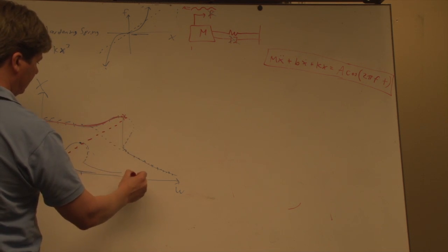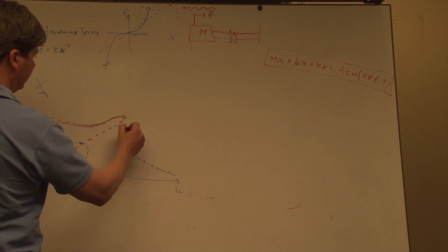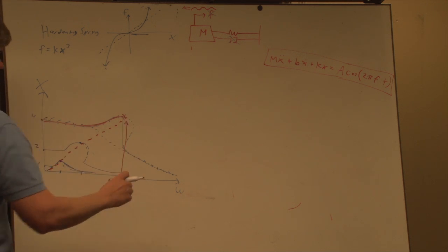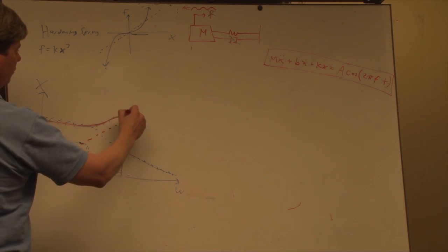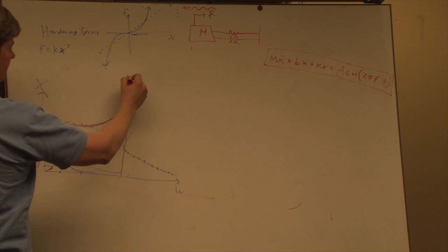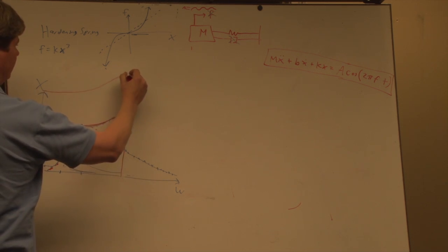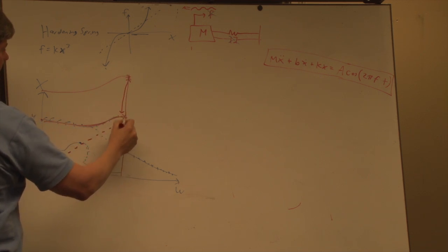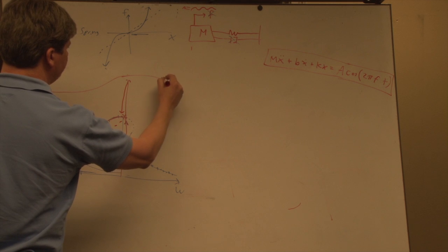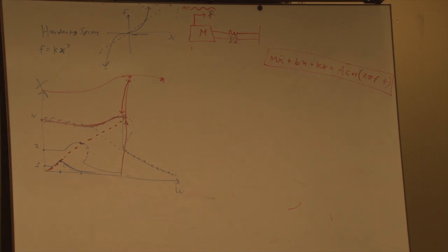But you cannot take this path to get to that point. You can't oscillate really fast and increase the amplitude and get to that point. What you'd have to do is get the amplitude way beyond where that's a resonant, where you're actually at a resonant curve here at a really high amplitude. Then once you have resonance, drop back down in amplitude, and it'll keep its resonance. And you can't push straight up. The amplitude will only increase to a point for a given frequency, unless you're ramping the frequency.